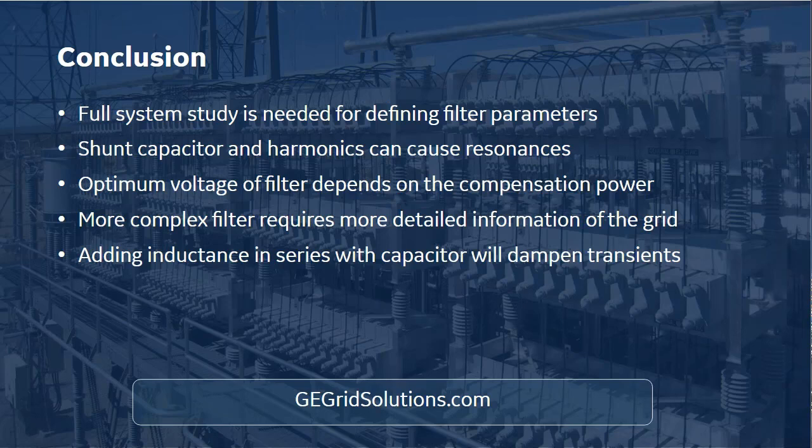For example, your requirement is that you have to be able to reconnect the banks very fast, let's say 1 minute or even less. Even in some cases it might be seconds. Then active filters are your only choice. We can reduce the reconnection time with passive filters also to quite a short time, but still we are not able to be as fast as with active.